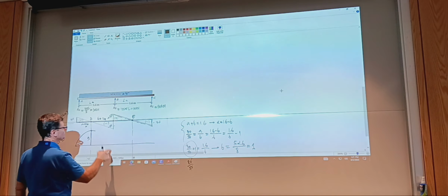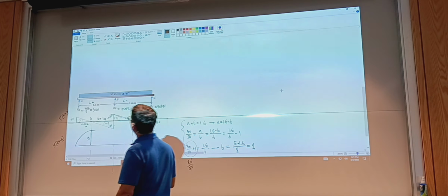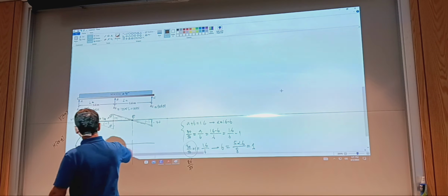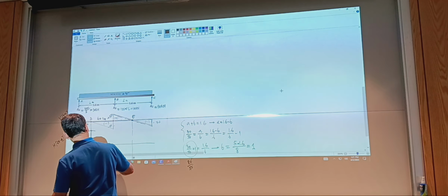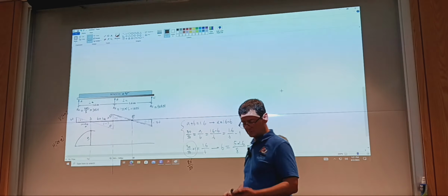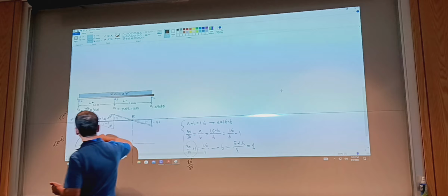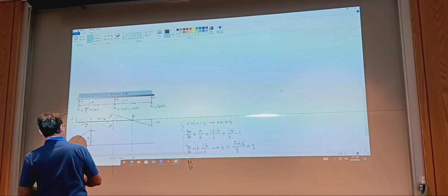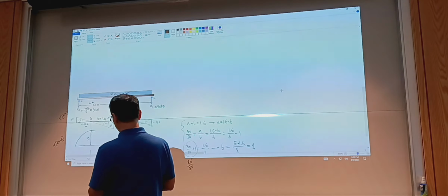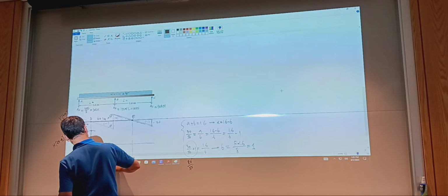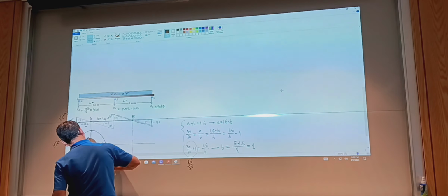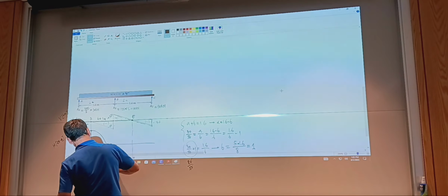And then this goes to some value at point B. Let's see if it remains positive or if it goes negative. In the appendix it appeared to have gone below the zero axis. So to get that, to 9, we add a negative area, or subtract 50 times 1 divided by 2. So 9 minus 50 over 2, that is minus 25, and it's negative 16. So it goes smoothly to negative 16.